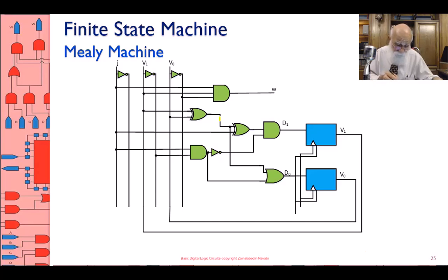All right, let's do the circuit. This is the XOR and then XOR again with J. But then V1, V0 XOR, then I OR it with the V1 J, that gives me D0. Then I take V1 bar J and complement it, and AND it with the 3-input XOR thing, this thing here, and therefore I get the input D1.